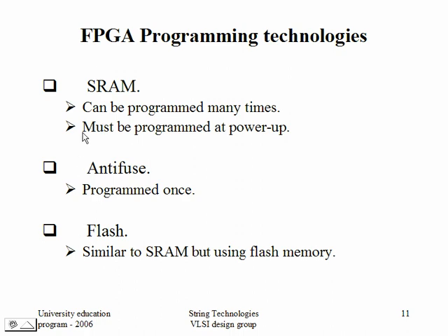If you see, these are the different ways you put the bit file in the FPGA. That's all. We are not talking about the architecture of logic cells, or the kind of routing mechanism. We are talking only in the context of how the bit file is programmed into the FPGA. Whether it is placed temporarily into the SRAM inside the FPGA, if it is SRAM based, or, if it is flash based FPGA, the bit file is programmed into the flash, so it becomes non-volatile. So we are looking at that option. We'll discuss now, don't worry.